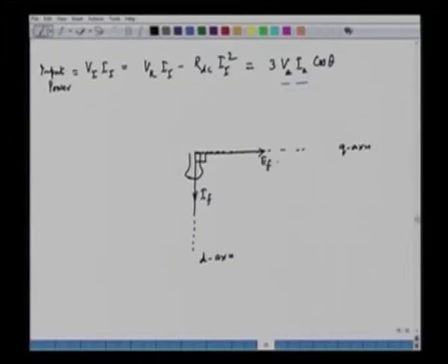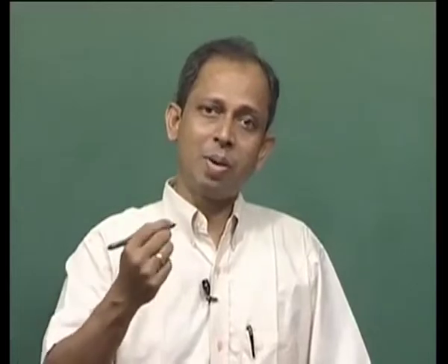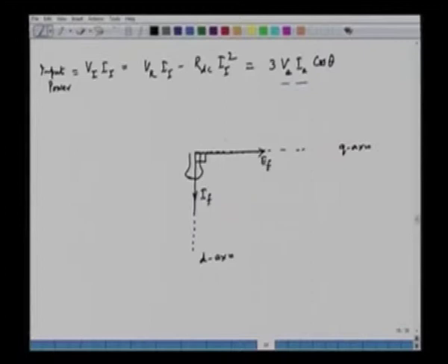We know that the induced EMF and the flux or the MMF are at right angle to each other. So, the EF is along the q axis and IF, which is inducing EF, is along the d axis. There is a quadrature relationship between the flux and the induced EMF, which is very well known from the DC machine. We know that the field is in the d axis and the induced EMF in the armature is in the q axis. Similarly, in case of synchronous machine, if we take the rotor reference frame, the field MMF is in the d axis and the field induced EMF is in the q axis. Then we have the current, and the current can be in any arbitrary direction based on the power factor. So, let us say that this is the current, armature current IA.